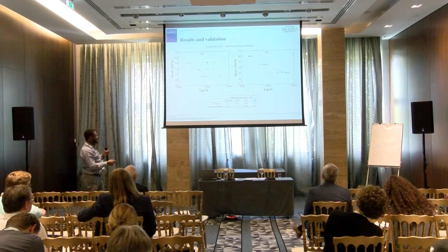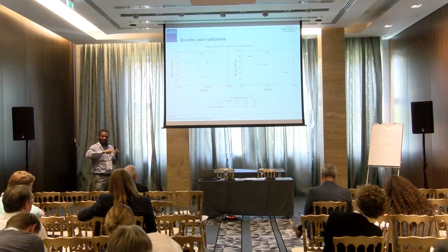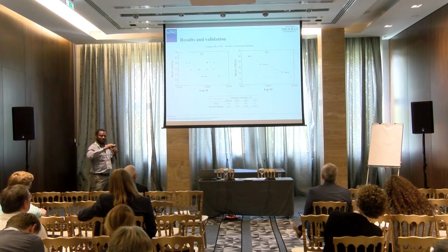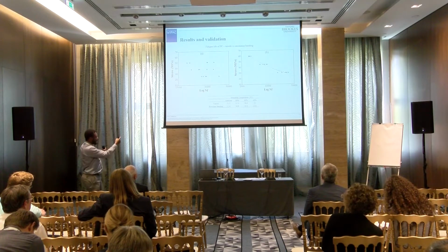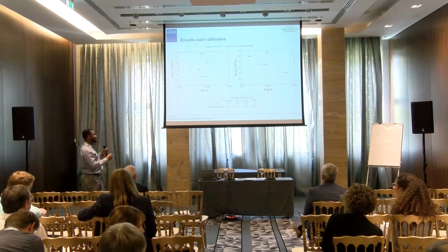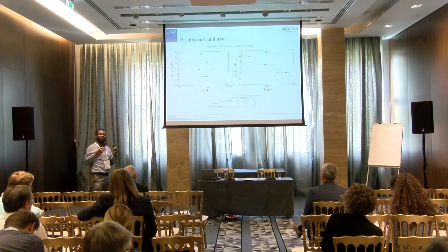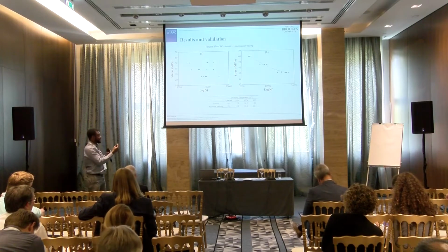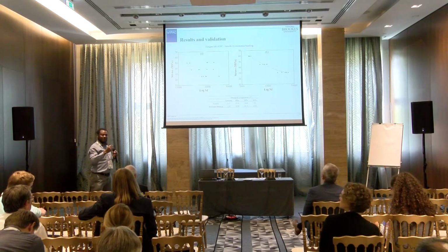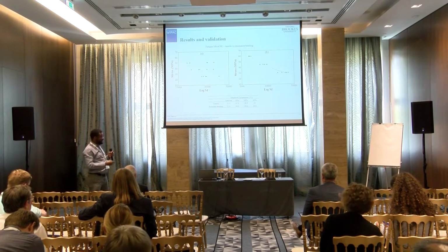If you look at 60%, it's a bit higher because the frequency is lower, the acceleration is lower, so the cooling is less. And then at 40%, the same thing, it almost equals the room temperature because the movement is very small. So in that case, it eliminates the effect of temperature. Even if you load it to a higher stress, higher acceleration, it will actually be good for the specimen. It will cool it down, rather than increasing, the temperature will be going down. So it's a very, very good system.